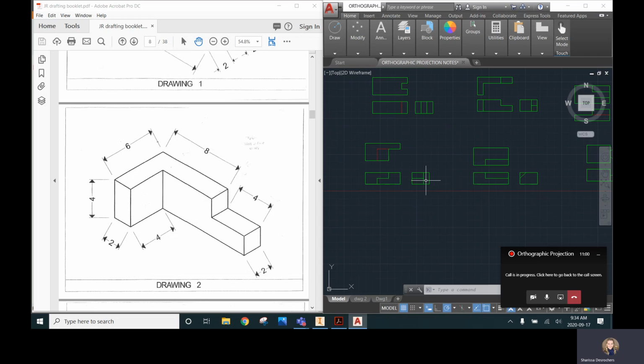First, you just have to level your paper. That's a step. Then you have to tape down your paper, and then you need a point of reference, and you have to measure it all out to make sure that everything is equal. Then once you have your paper set up and your border set up and everything is equal, you can start drawing. You draw your first line, then you get your triangle and draw your 90-degree line and get your first shape lined up. It's so much work to do that.